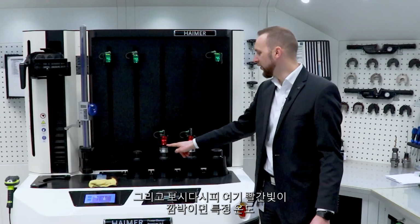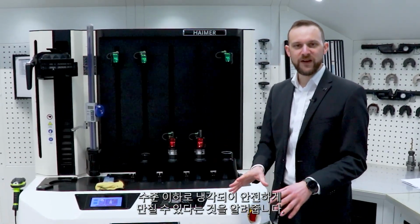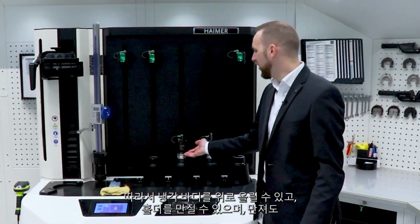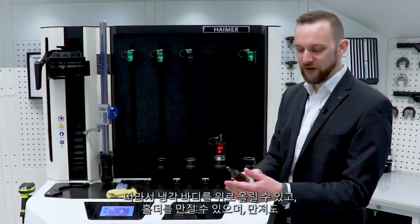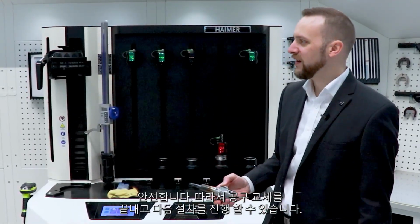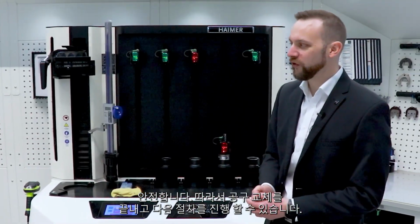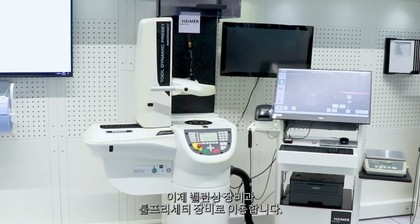And you already see now here, it's flashing red, telling us now we're beneath a certain temperature level, it's safe to touch, and therefore I can move up the cooling body, I can touch the holder, it's safe to touch, and therefore we can go on with the next procedure and changing the tool. And that means we're going to the balancing and the presetting machine.